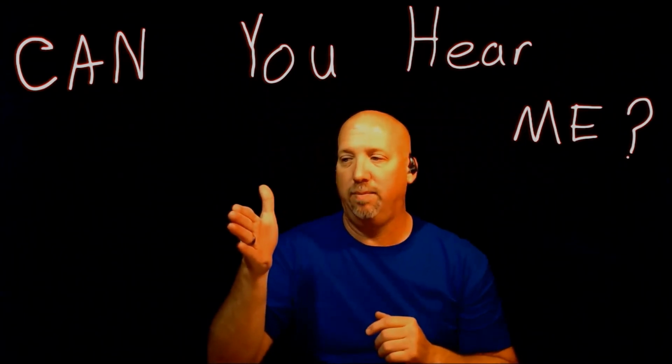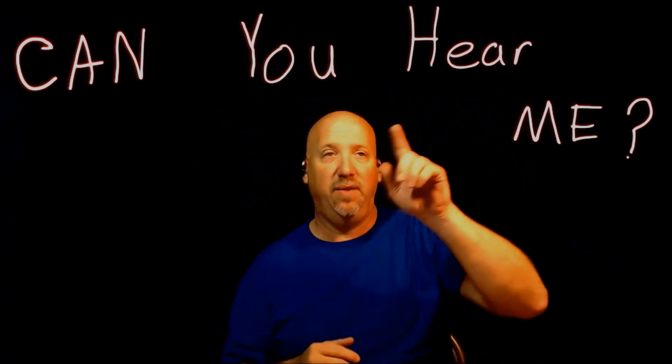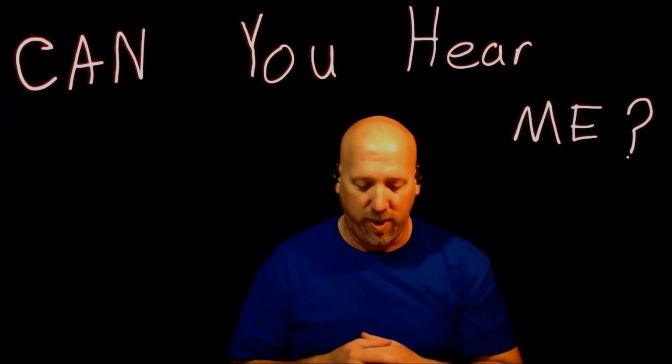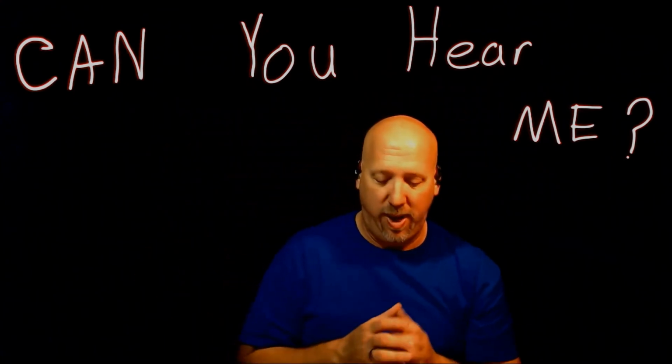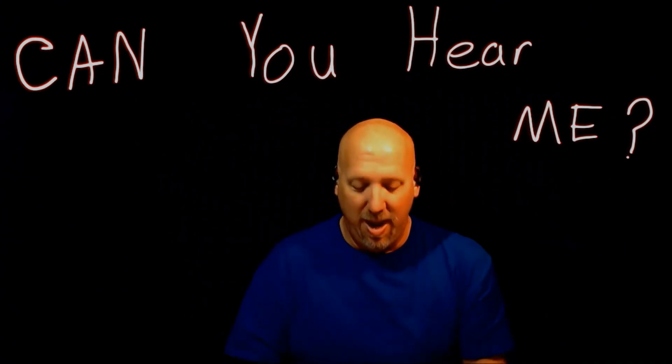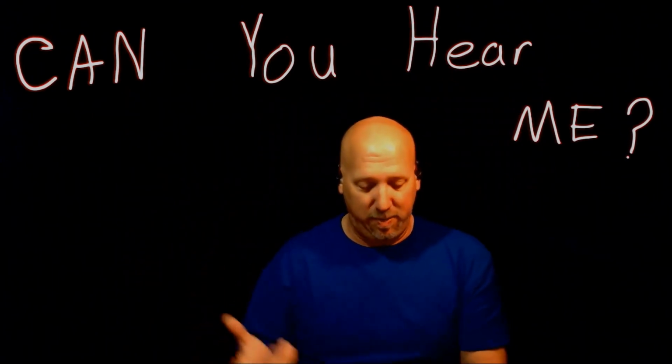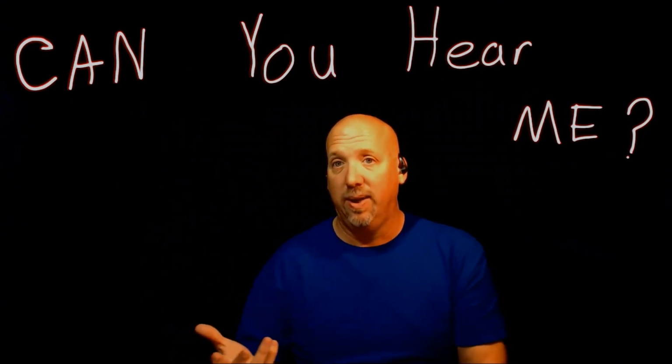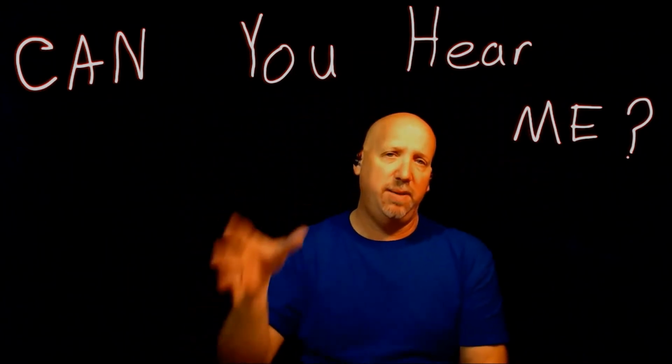A message starts, and there are identifying bits that let the modules know which module it wants to communicate with. That way the other modules will ignore it if it's not that module. The priority bit helps the other modules know to shut up to allow this communication to occur. After the message is sent, it's followed by redundancy bits just to make sure the message is valid. Just because it sends a message doesn't mean it's a good message. The redundancy bits behind it say it's a good message.